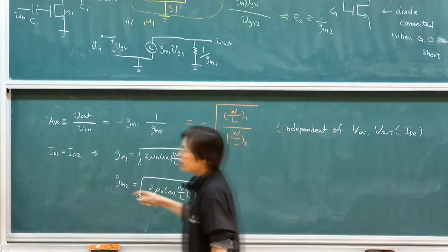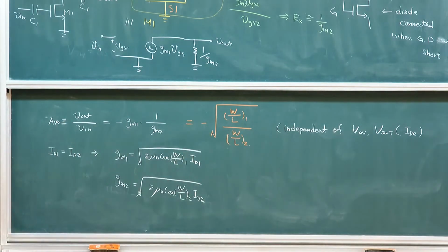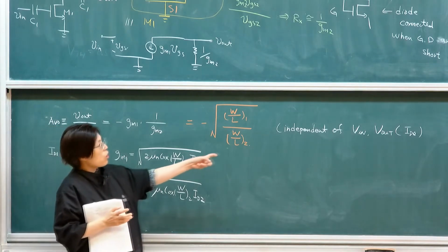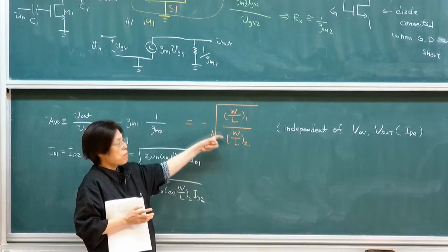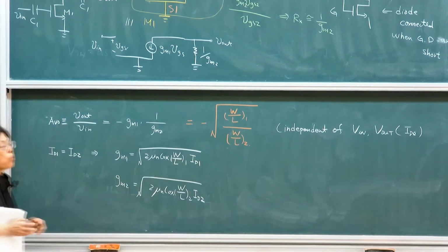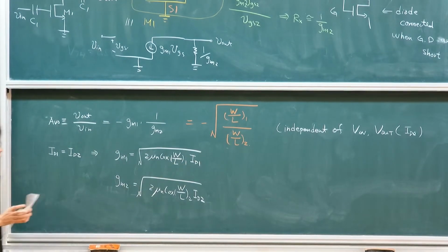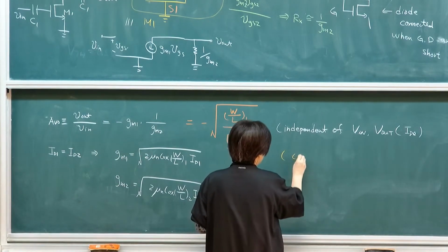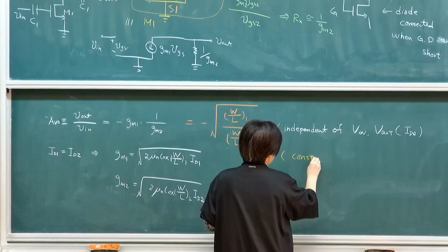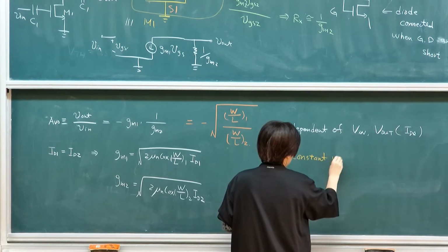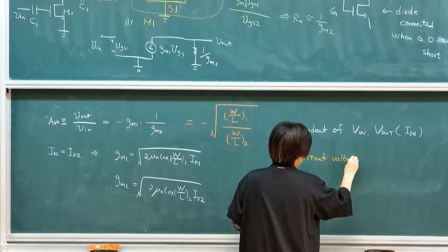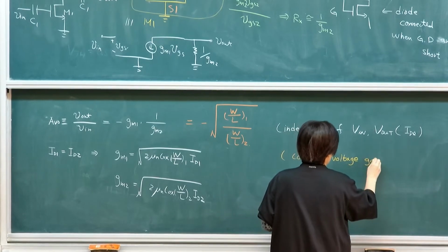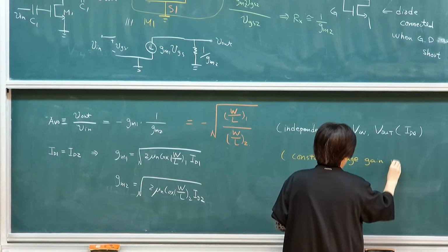The reason why we say that this is not a linear gain is because it will change. gm and ro both depend on current. In this case, there's none of that. It only depends on device ratio. So once this has been made, it will then provide a more linear amplification. So it will then have a more constant gain without